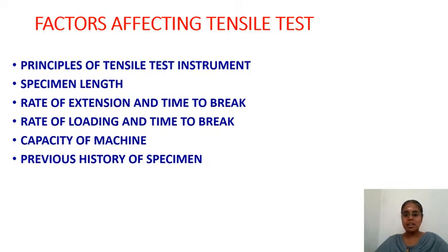If the specimen length or the gauge length is higher, there is a probability that there will be more weak links. So it is bound that you will have a lower strength reading. You have to be very careful while assigning a specimen length, and they have standardized the specimen length for a particular type of test. Say it is 300 mm for a single yarn strength. For single fiber strength, it is lesser. For fabric, it is say 12 inches. According to the type of test, it varies.